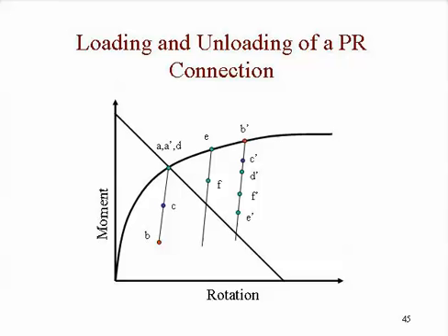Well, if I take off half of the lateral load, the connection on the prime side, which is the one that was increasing due to the lateral load, now decreases along the straight line, the unloading initial stiffness. The one that had unloaded down to here now loads back up to C. But notice that now that is a linear behavior. So now we're at C and C prime.